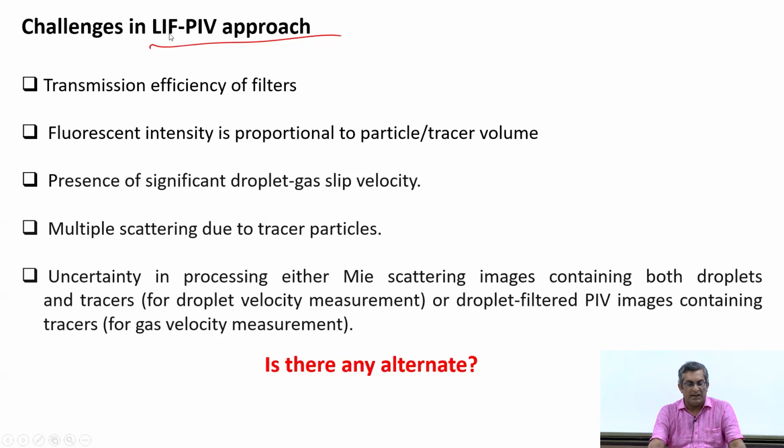So for the LIF PIV approach, if we only restrict to dilute loading, the advantage is that we can get two-phase measurement with good accuracy. But the problem is that PIV cannot provide particle size. So what you measure is basically particle velocity and fluid velocity, but you don't know particle size. And if particle size is not known, then the results may not be meaningful.